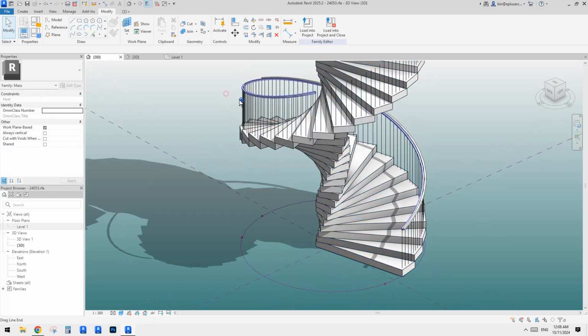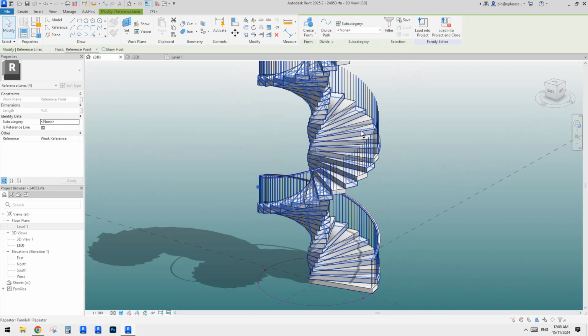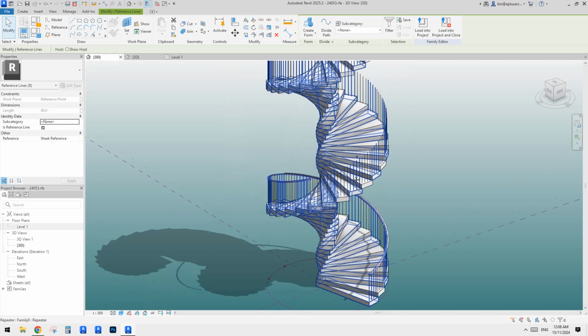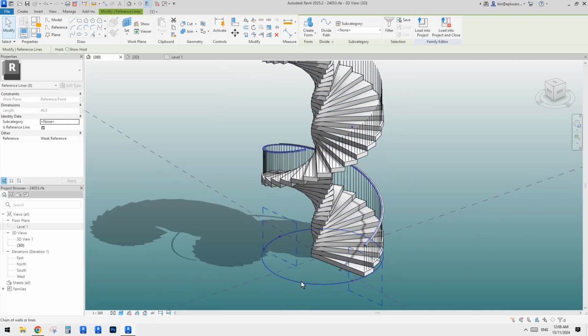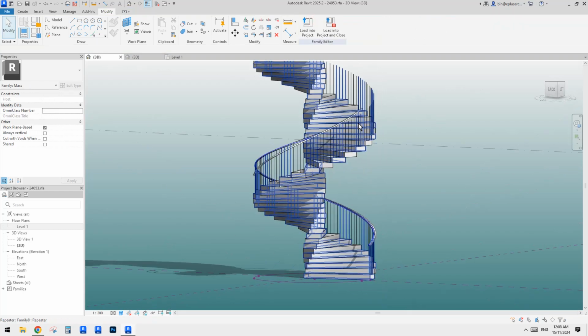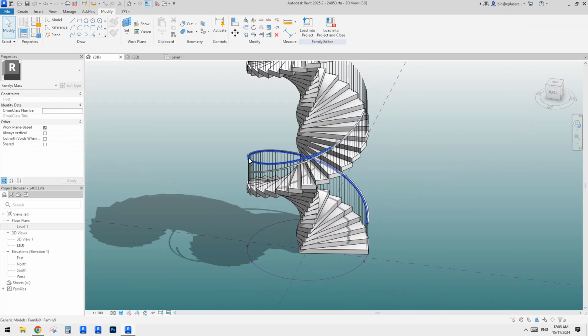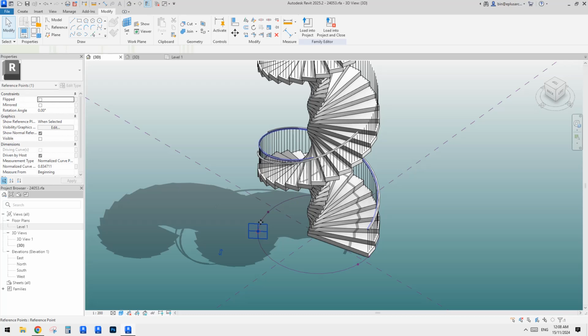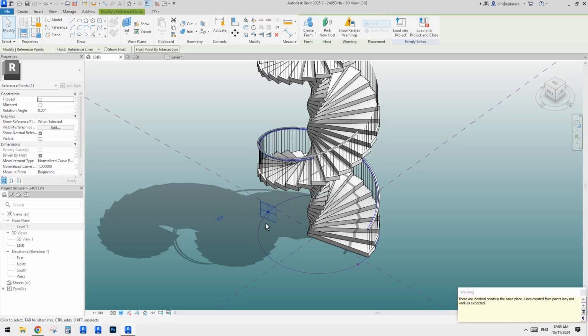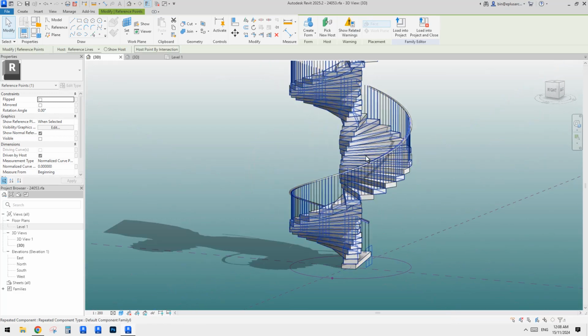select this profile together with this one, the one we just moved up, and also this profile. So make sure, see, if you do not use tab, it will select the whole thing. Tab selects only half of the circle, so create a form. You might say, oh, it's not matching because we need to move the point to the end, right? So this one move to the end. Now you will see, that's it.